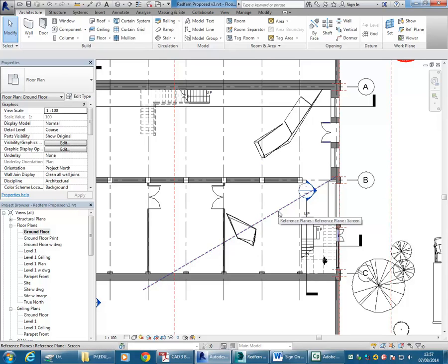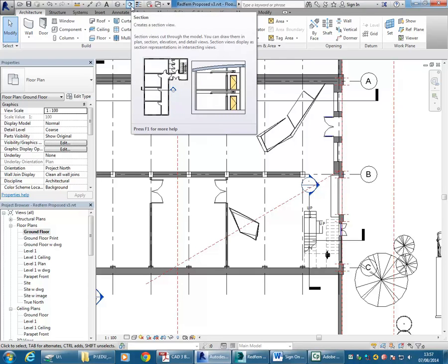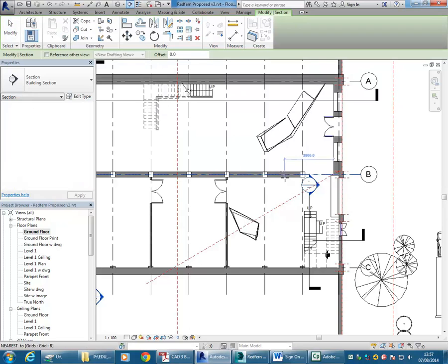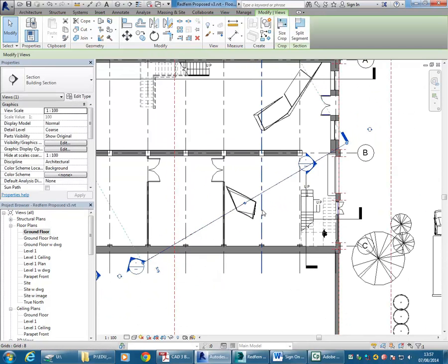But also, I'm just thinking ahead, I've got to have a view that looks at this plane. And so another really useful trick in Revit is to draw a section outside of the family. Using the section tool there, I'm going to snap to that plane. Another really good trick I've worked out. Snap it onto the reference plane that you're drawing against, or drawing parallel to, or perpendicular to. And so I'm looking basically in the same direction as that plane. Just going to use the arrow keys to nudge that down so that it's looking towards it rather than sitting right on it.